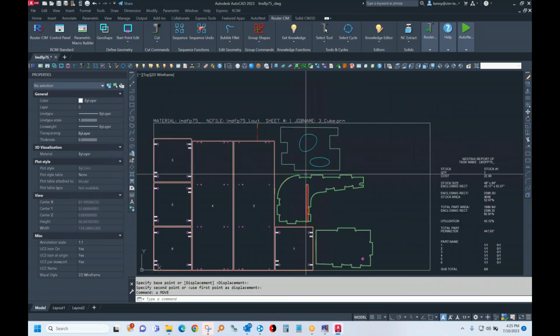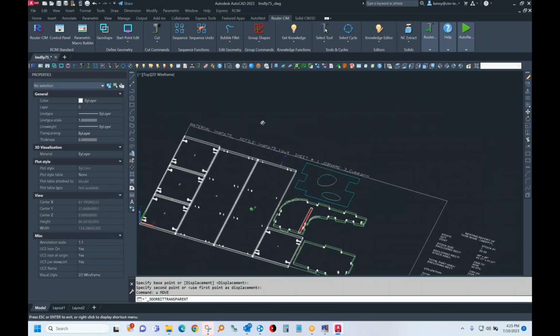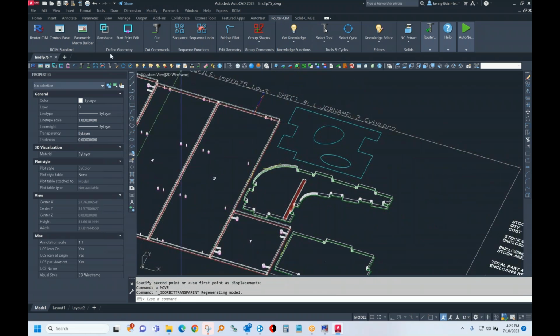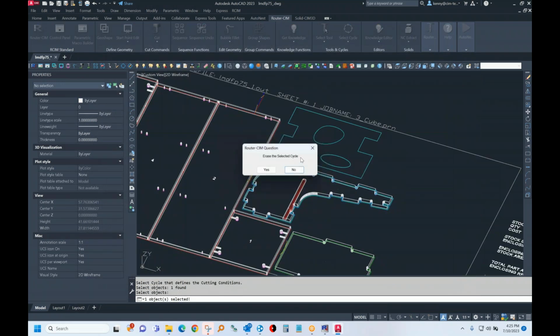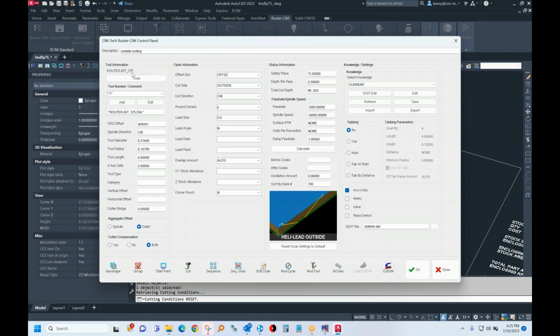Okay. So even though I just drew this in 2D, I could start making my tool paths. In fact, let me get the information from this part here. I could pick a button that says retrieve this tool path, optionally erase it. Oh, that was a 3/8 bit in tool number 1, doing an outside cutting, going through the material by 3/1000ths, or I could just plug a specific depth in right there.